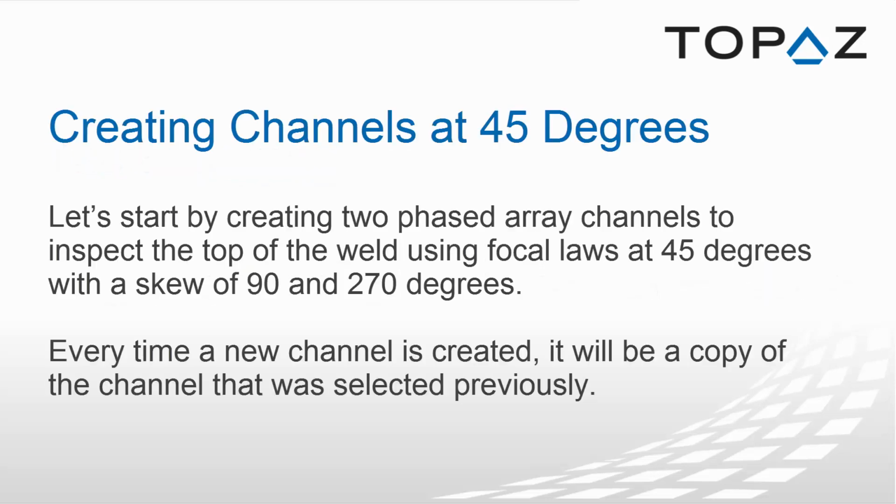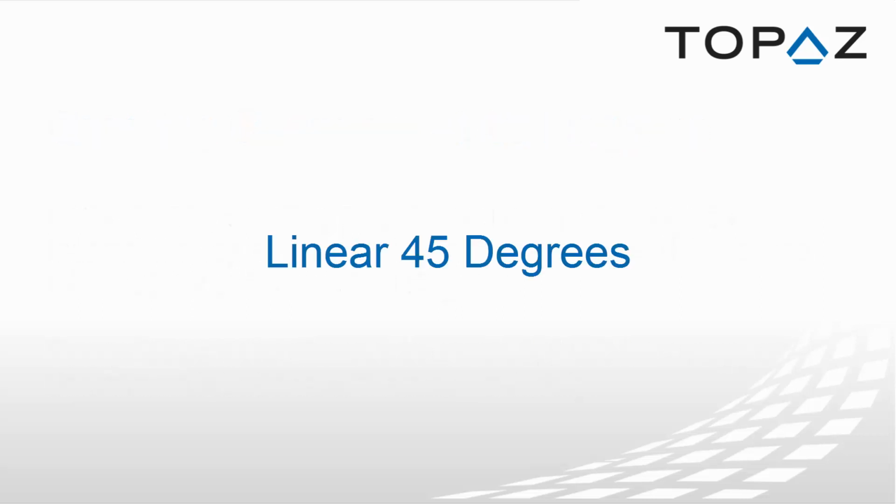Creating channels at 45 degrees. Let's start by creating 2 phased array channels to inspect the top of the weld using focal laws at 45 degrees with a skew of 90 and 270 degrees. Every time a new channel is created, it will be a copy of the channel that was selected previously. We will do a linear at 45 degrees.